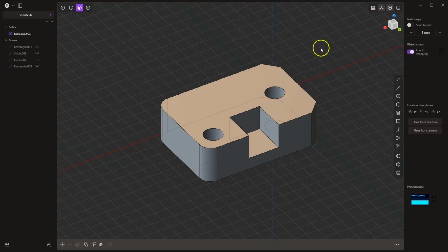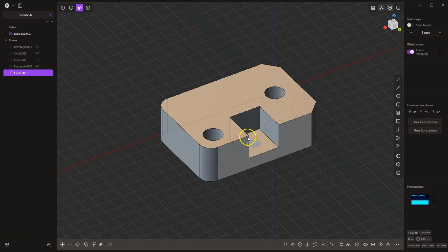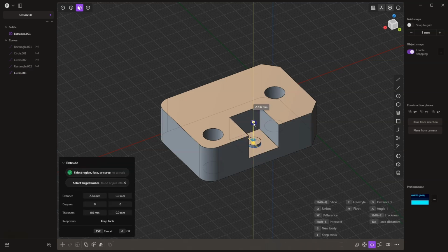Now I will show you another trick. I will create any geometry here, and I would like to add the extrusion of this solid to the height of this face. To do this precisely, if we know the height of this face, we can enter a specific extrusion value, but if we don't know, we can simply press the Control key while adding the extrusion and hover over some geometry that is at the height of this face, for example, this point. Here I release the left mouse button, release the Control key, and the extrusion has been made to the height of this face.